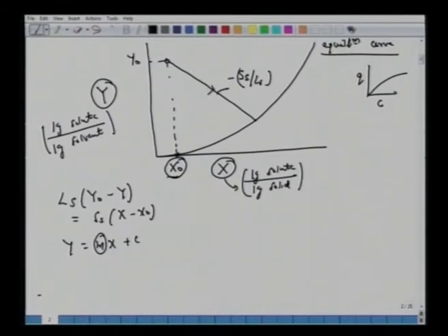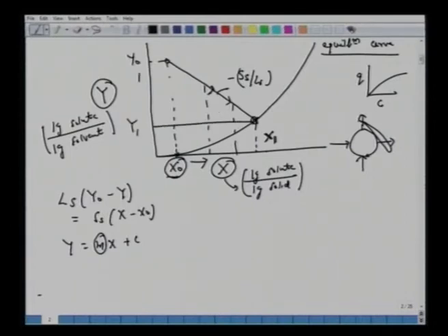So the concentration of the liquid phase will decrease and the solid phase concentration will increase in these directions till we hit the equilibrium. If you have ideal stages and we are assuming that the two streams have spent enough time, then the spent solid and the treated feed will have concentrations which are in equilibrium, given by this equilibrium curve. So essentially we have come down to x1, that's the maximum you can increase solid phase concentration, uptake, and the lowest you can come down is y1. So y0 to y1 and x0 to x1 here.